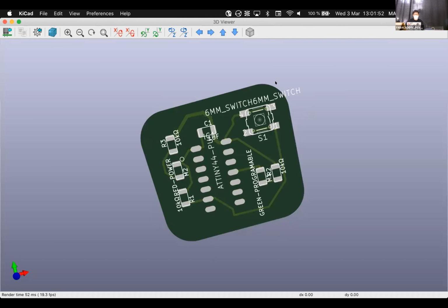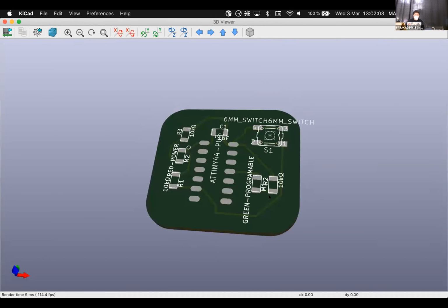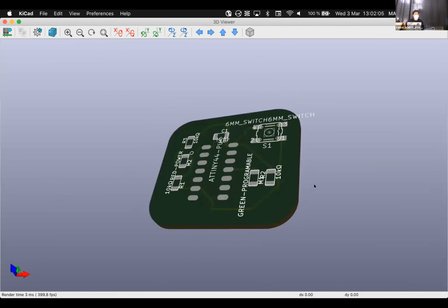It means that the actual profile that you did outside is really closed, is not opening in any point, and the program is able to determine the PCB. And this is actually how the PCB is gonna look. As you see here, you have some of the buttons. You see that this is actually gonna be printed on the PCB if you send it to manufacturer. You won't see this on the milling machines unless you put them explicitly on the copper layer.